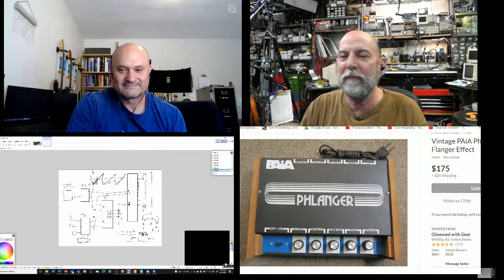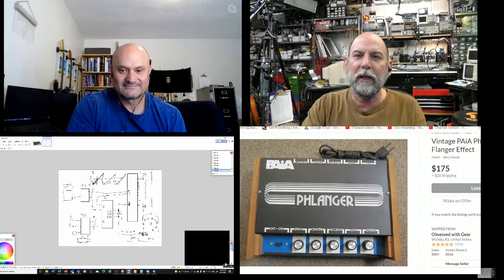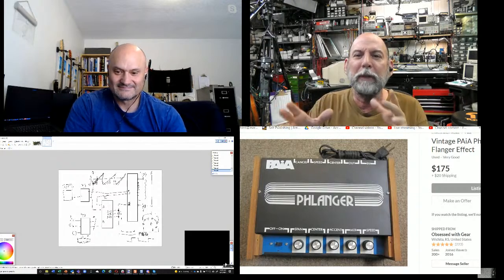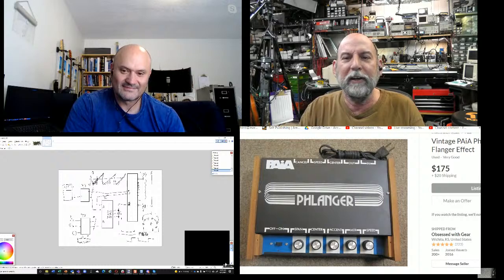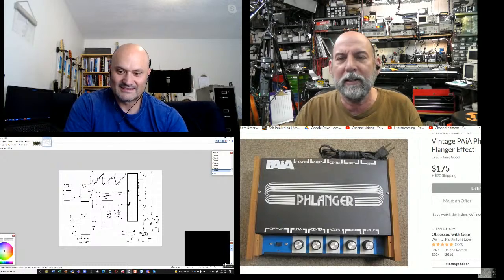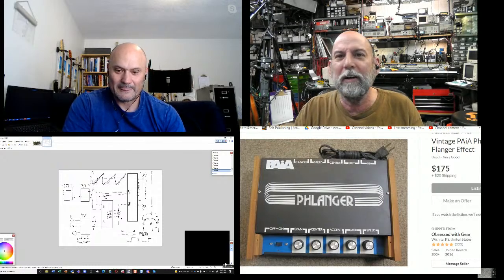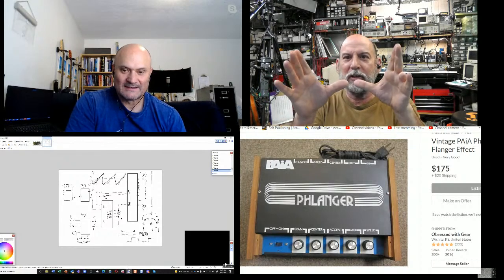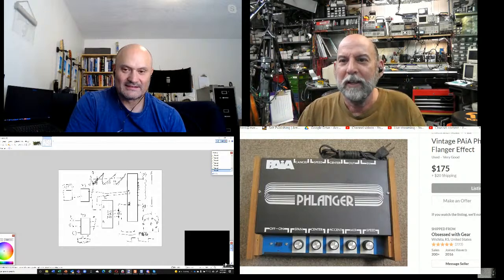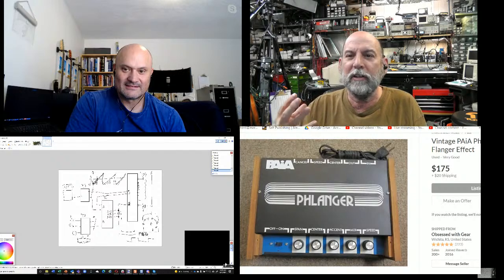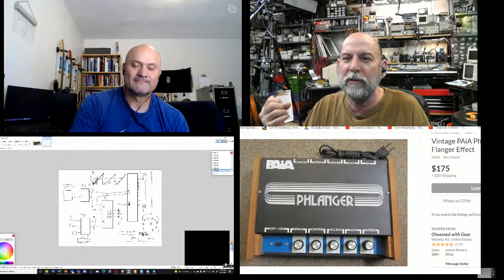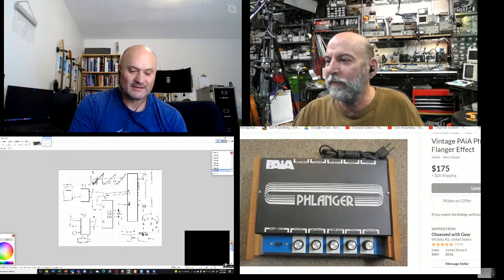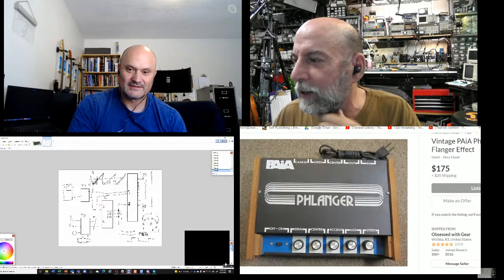But it had a VCO and a VCA, voltage controlled oscillator, voltage controlled amplifier, low frequency, all the little pieces of the synths at the time. It also came with a lot of noise in it because it was only a circuit board this big, so it was single transistor circuits as opposed to five or six to make a real low noise VCO. So yeah, I forgot all about Paya till I Googled it just now.